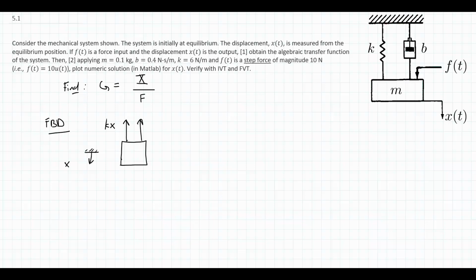Because again, when x is positive, this quantity will then be positive, and if x is negative, it's going to be compressed, and then the quantity, the product, is going to be negative. And that's what we want to happen. Positive tension, negative compression. Now again, we're assuming, and for the most part we are always assuming, springs are going to obey this linear relationship that the force in the spring is k times x, and that is, unless otherwise said, what we're going to be assuming.